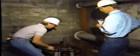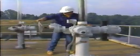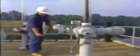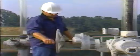If possible, look to see that the gate or valve moves evenly. Jerky or rough operation, excessive vibration, abnormal noises, and binding are all signs of trouble. Also, check the mechanical equipment that is used for emergencies. Auxiliary power systems must be in good repair and should be test-operated periodically at intervals specified in the standing operating procedures.